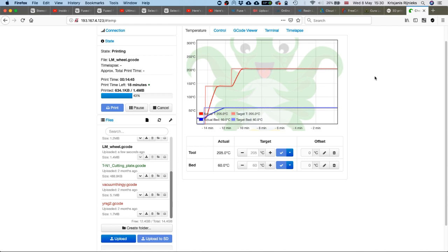Also, the infill is decided by the slicer, how it is structured in the volume, right? Like the rabbit that we saw in the YouTube video with the silk. Yeah, so it depends on the slicer. You can also specify some settings, so you can make it triangular or rectangular or honeycomb, or any other shape. Well, not any other shape, but the shapes offered by the slicer, because it's also the strength that you require for the walls. You should take that into account.